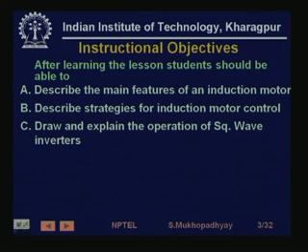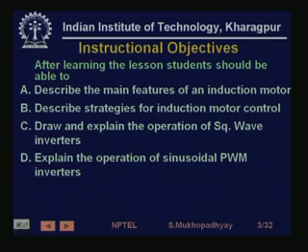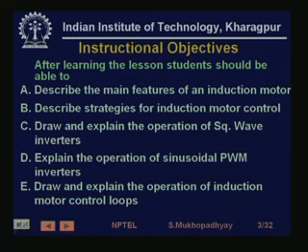how we go to the technology side and see that there are two kinds of induction motor. It is an AC machine, so it uses inverters. Actually it can use various other things, but we will look at inverter driven induction motor drives. We will first look at the square wave inverter, which is a simple inverter, and then we will look at the PWM inverters, which are more complicated devices but have advantages, and finally we will see what an induction motor control looks like.